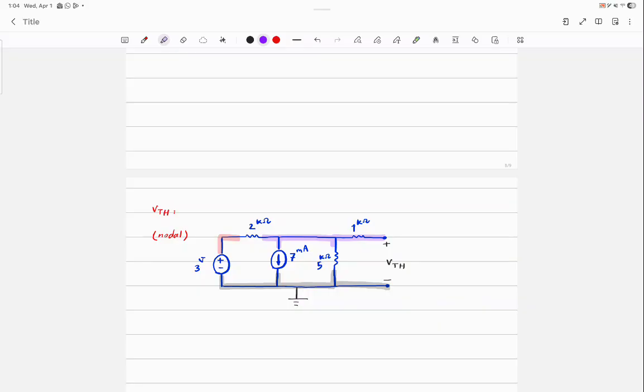I shouldn't have ran over the 1 kilo ohm resistor, but I did. Why? That guy is part of an open circuit, so it doesn't have any voltage drop. So it's not creating new nodes for you, right? What do you label the purple one? VTH.